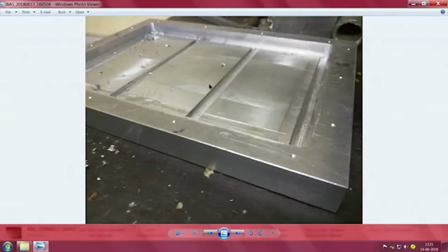And our electronics engineer Professor Rumanand has suggested, if we make all the openings a little larger, is it possible for us to make a simple thermosiphon? If you just need to tilt it a little, maybe keep it at 60 degrees or so, maybe the fluid will all come here and go that side, and we can avoid one unreliable pump. If we avoid the unreliable pump, we have something which is passive.